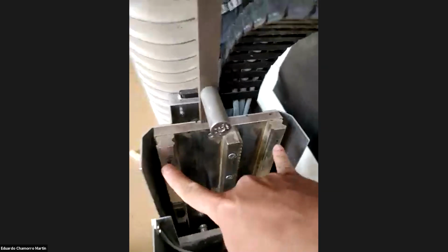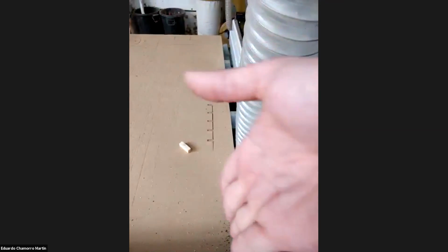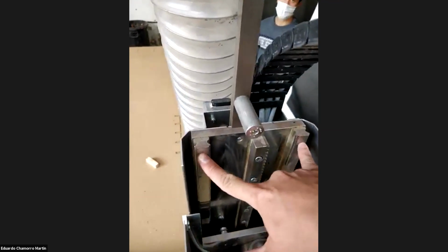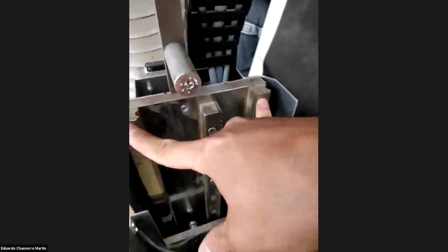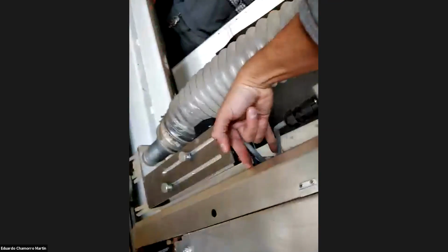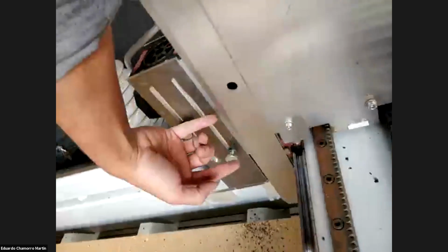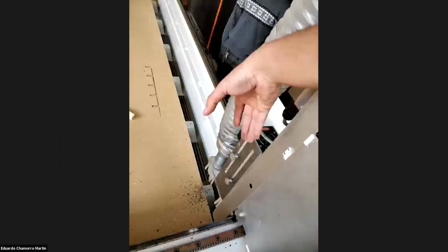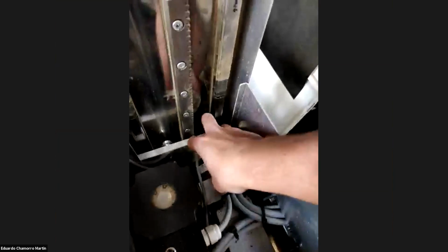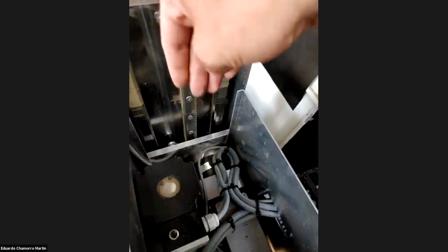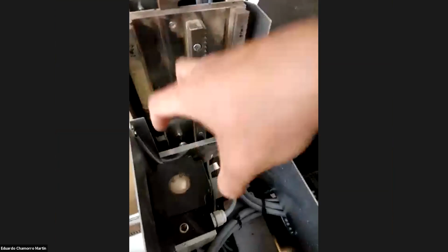So here we can see that we have the linear movement. The Z needs a lot of strength to not bend. Actually, in here, for example, we have a double linear bearing, quite huge, and the bearings are inside, and they have 4. They have 2 here, and 2 here. We don't see them, but they reinforce a lot the side movement of the axis. And we have the big motor with a reduction gear, because this axis is moving in small amounts, but needs a lot of force to push it.